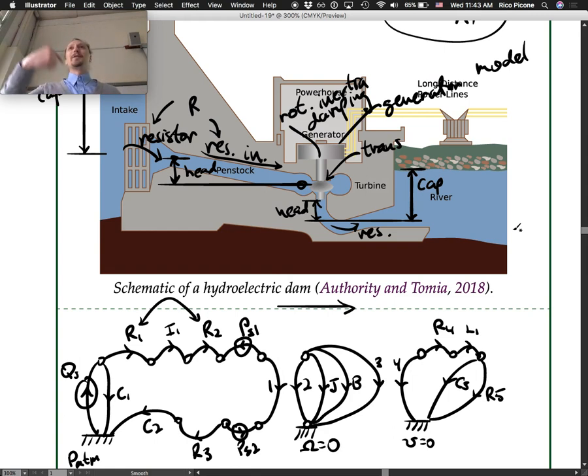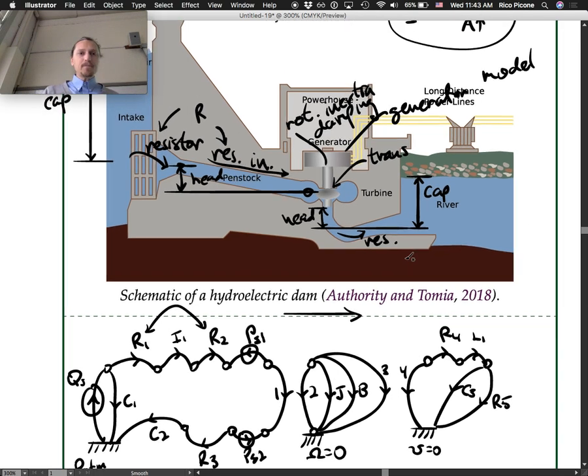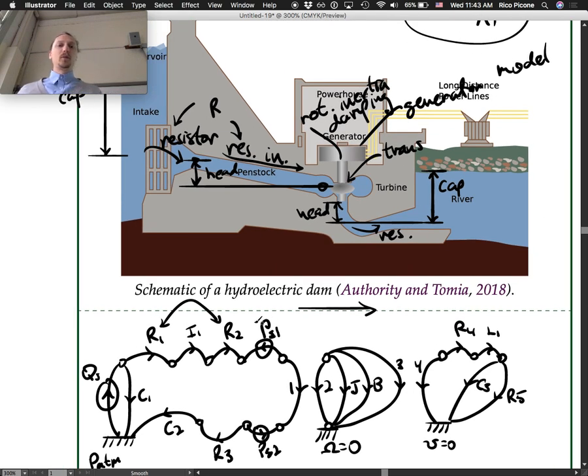Yes. I'm wondering where the pressure, P sub S1 and S2, come from. Yeah, so PS1 and PS2 are modeling these 2 constant heads that we have in the system. We've got two different heights here and here that this pipe flows through. So we recognize that when you're at 2 different heights, the hydrostatic pressure is different there.